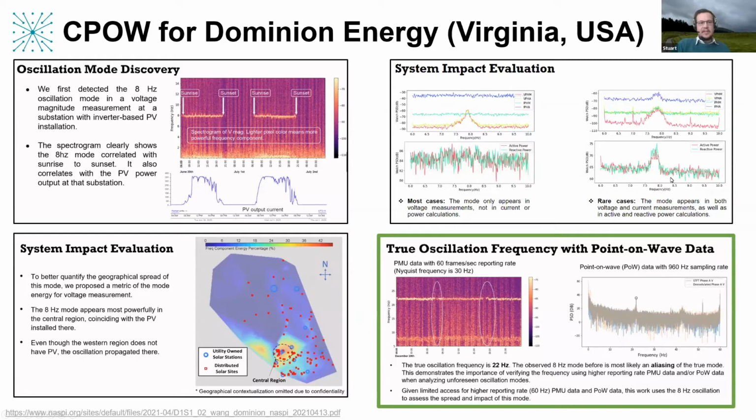Yeah, thanks, Stephen. We've seen similar to this example from Dominion. We've seen similar behaviour in other places in the world, including in the UK, in work we did on the Visor project with Scottish Power, SSE, National Grid. We see these kinds of high frequency oscillations. I say high frequency, particularly in the subsynchronous range, so anywhere above the 2 hertz where the electromechanical behavior ends, up to 46 hertz or just below the synchronous frequency. There's more and more power electronic equipment going onto the grid, throwing out these kinds of oscillations.